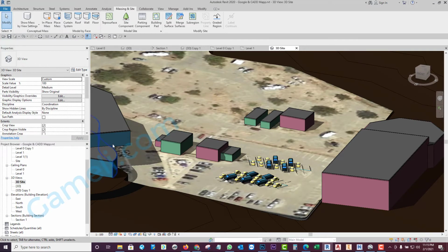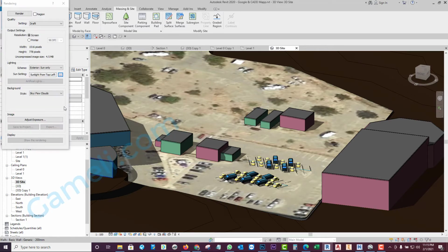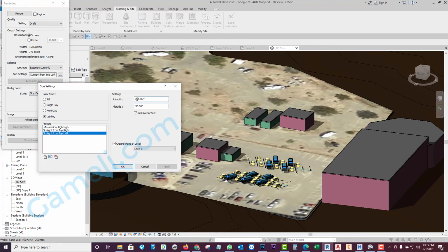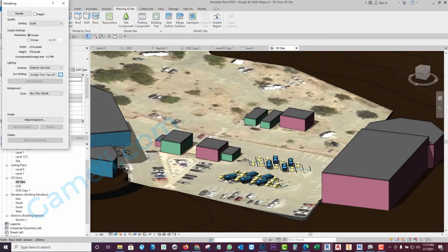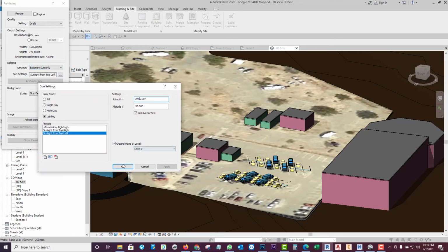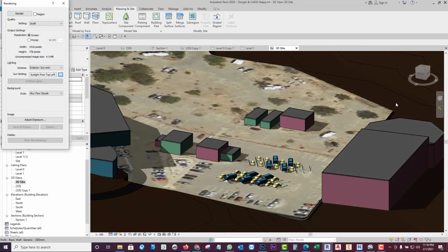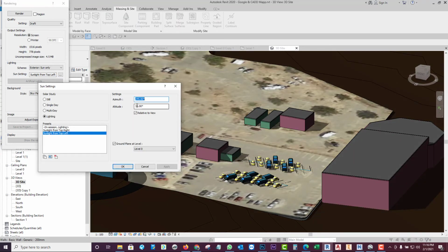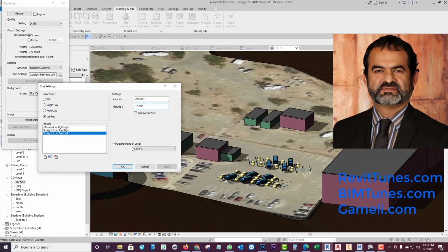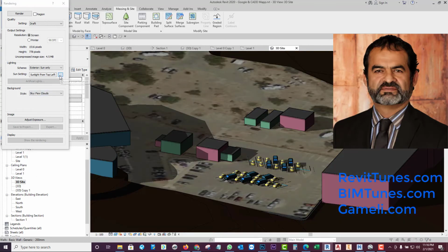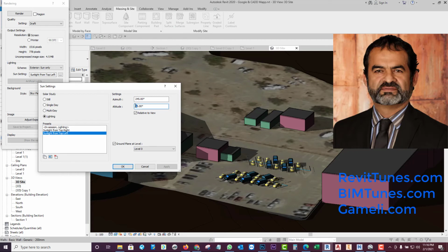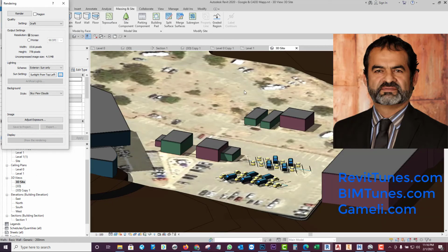You choose the best. In fact, you could change also the angle. If I go back to the window, let's say I want to put here 205 degrees. Okay, so it moves in that direction. Or if you put 45, I got it, 45, so it goes in that direction. And if you change the angle to 15, let's say, it goes more in angle, so it's getting darker. Or if you get 45 or 55, now the sun is in a different angle. So you could mess around with those parameters and get your best image.